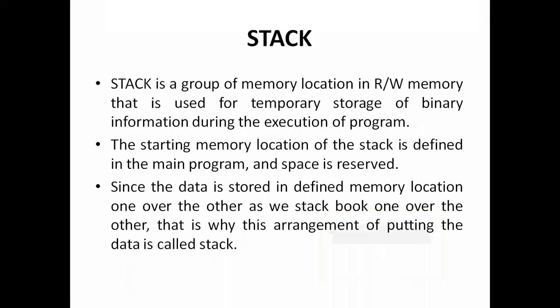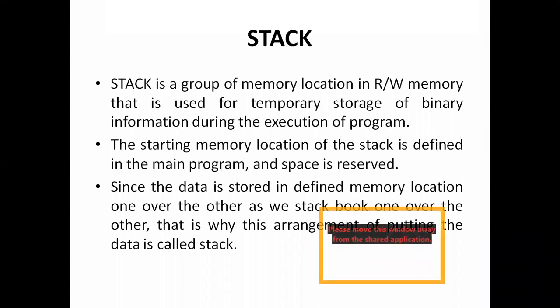So let us go with the simple explanation of the stack. Stack is a group of memory locations in the read-write memory that is used for temporary storage of binary information during the execution of the program. Many times, whenever we are executing a program, we need to put data somewhere in the memory so that it cannot be lost. And whenever it is required, we are able to fetch it.